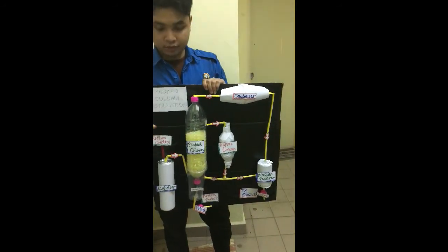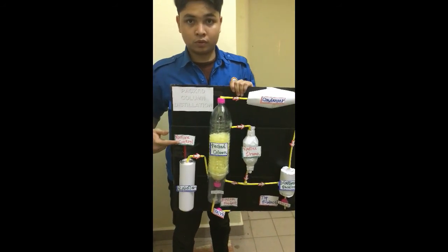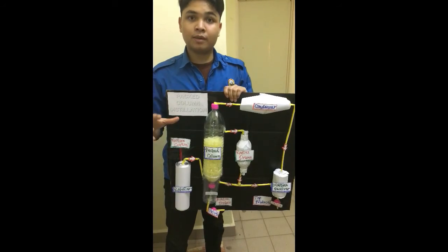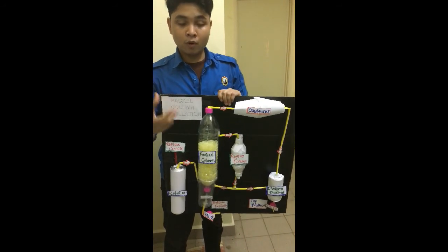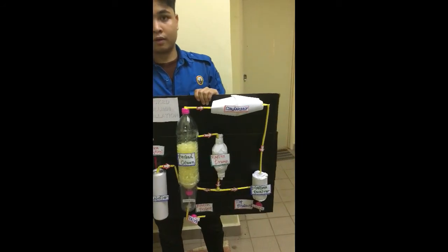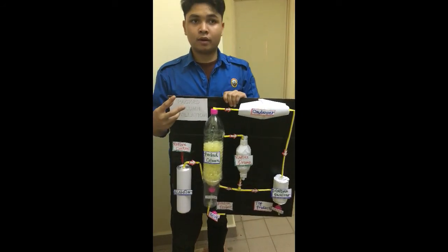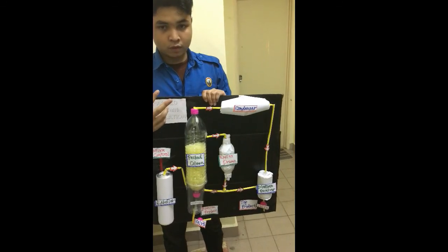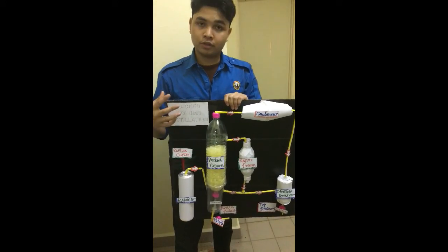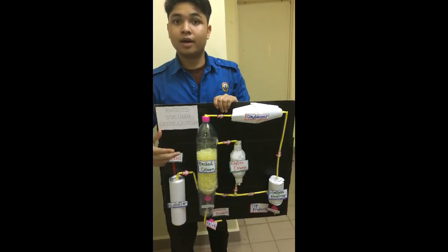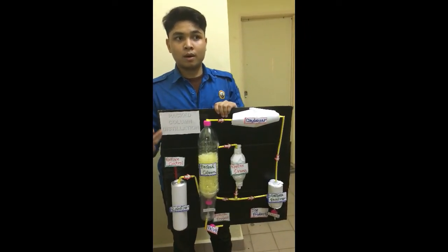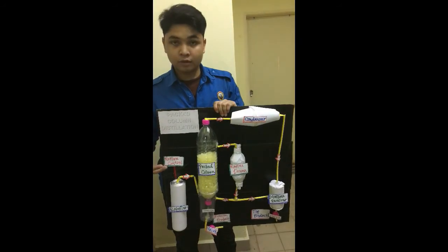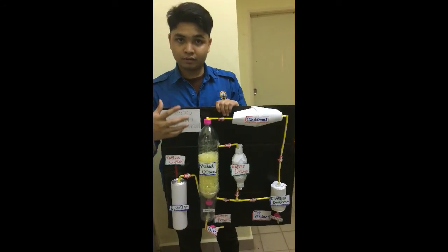The reflux drum is controlled by the reflux control. The reflux can be adjusted in order to get more purity of the product. For example, we set the reflux to two values, which are reflux ratio 1 and reflux ratio 2. As a result, reflux ratio 2 will produce more purity of the product compared to reflux ratio 1.